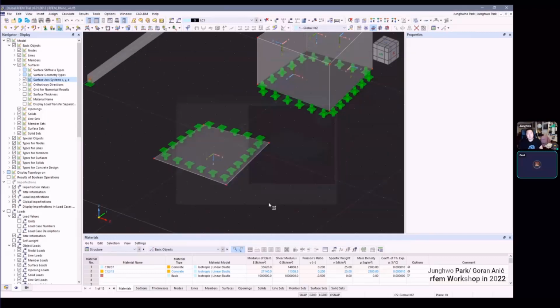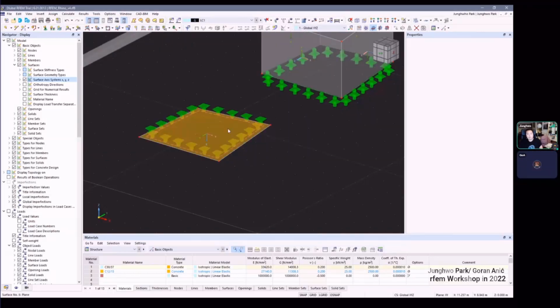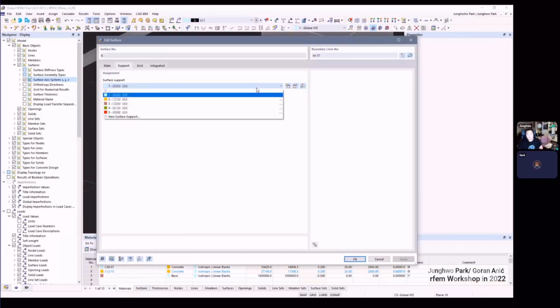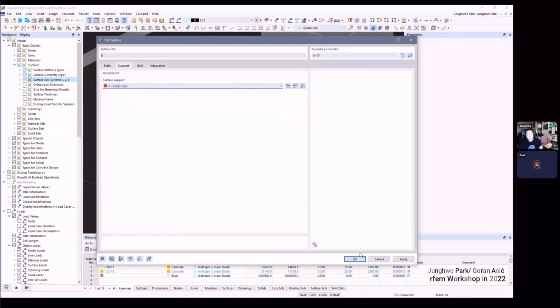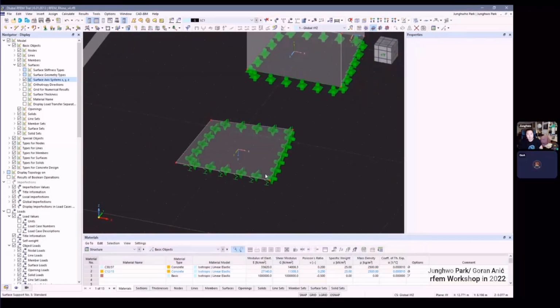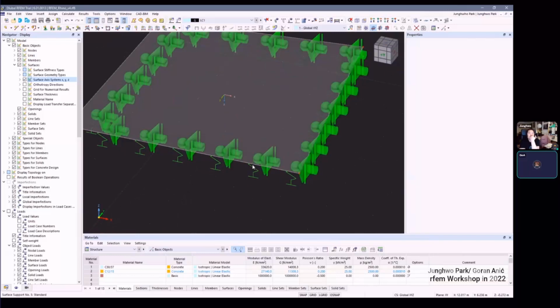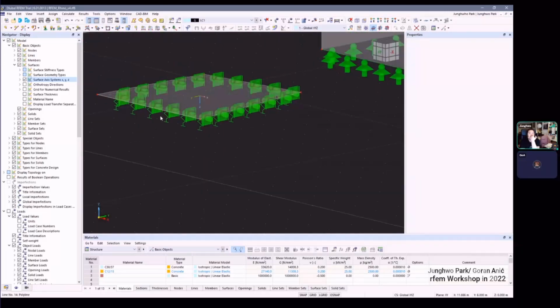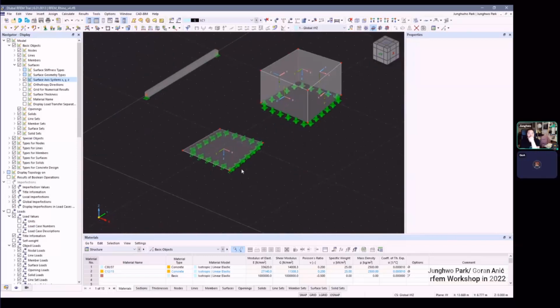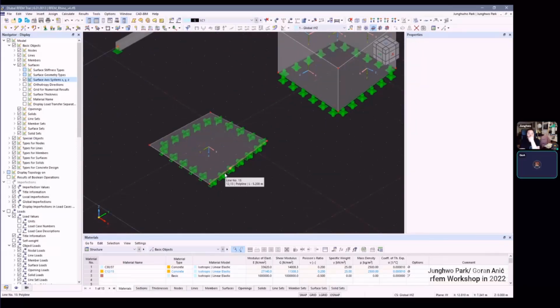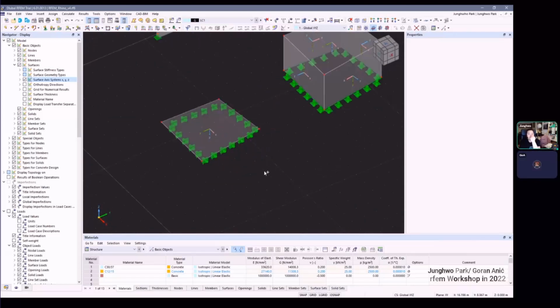Now I get under my slab the second... Did it change? Sorry. Okay. You see, we get some spring condition on the side. So it means when we put some forces on it, our foundation will not give 100% reaction from the bottom. First, it will go a little bit down, and then it will react with some force. This will be the bedding option for the foundation slab.